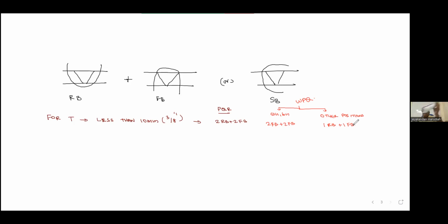If you take a pipe, if the welder is welding like that and the pipe is rotated, this is 1G rotated. Pipe is fixed, welder goes around and welds, that is called 5G, and it is called multiple position. Why multiple? The welder is welding here overhead, here vertical, here flat. Then the pipe is like this, the welder is welding here, it is horizontal, 2G. This is 2G, this is 5G, and at 45 degrees we call it 6G. It need not be exactly 45; a 5-degree deviation is allowed. For horizontal, a 15-degree deviation is allowed.